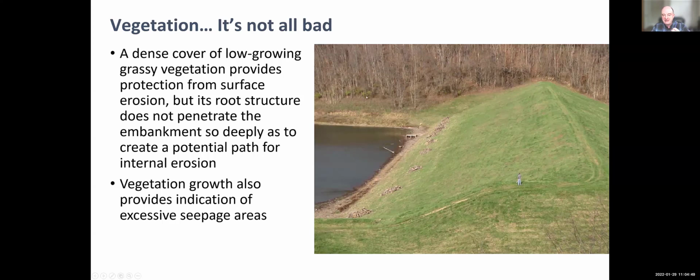This is probably suggesting they don't have a boom on this particular dam. But looking at the dam itself, that's what it needs to look like. You can see in the groin area over here, they push the vegetation back far away from the dam. So you can see the whole thing. It's easy to inspect. It's easy to detect deficiencies in that dam if there's slumping or seepage.